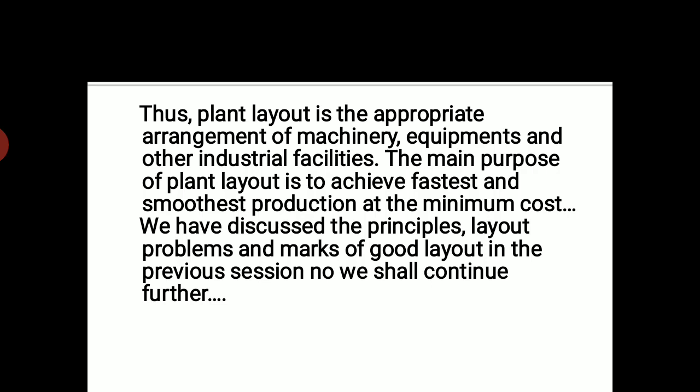I repeat one more time, what is layout? Thus, plant layout is the appropriate arrangement of machinery, equipment and other industrial facilities. The main purpose of plant layout is to achieve the fastest, smoothest production at the minimum cost. We have discussed the principles, the layout problems and the marks of a good layout also.